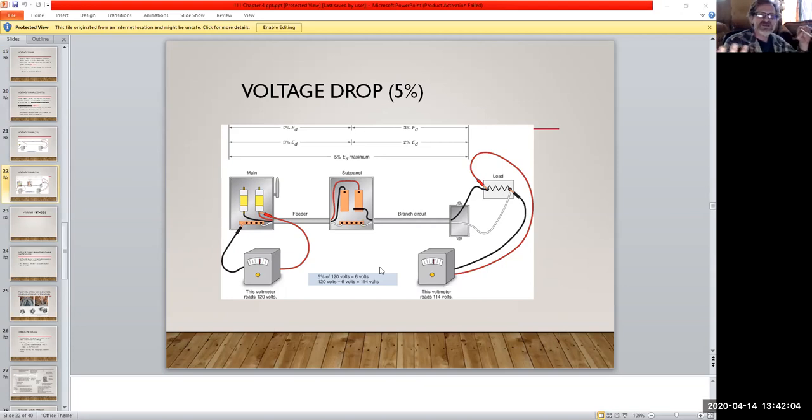So in the case of the AC, if the circuit breaker's inside of the house, or even in the garage, and you're in the back of the house, you can't see if somebody else is going to come along and flip the switch, right? So this is a safety thing. Usually you'll have a sub panel for disconnect, so you control when you're working on it, right? We never, ever work on live stuff.